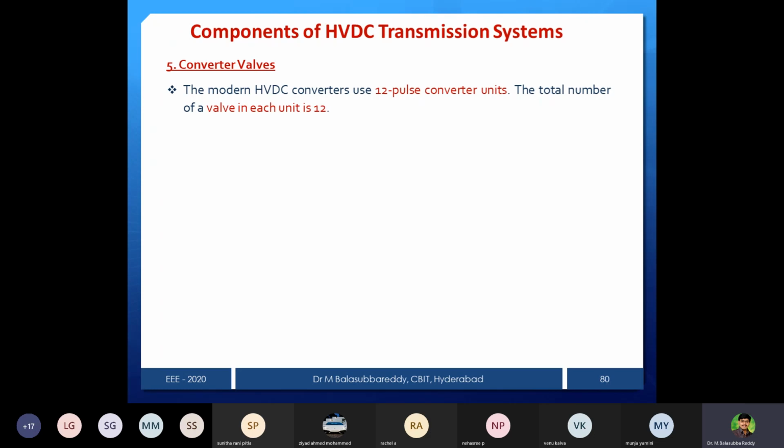Pole voltage means the VDC output, but at the positive pole and at the negative pole. So what is the voltage at the positive and at the negative pole waveform, and if overlap is beyond 60 degrees, what will happen? All the analysis in detail we'll see in the second unit. With overlap and without overlap, both cases are there, and we will try to draw the waveforms for analysis purposes. That is very easy, and the only thing is we ought to form one table to draw all these things with different angles.